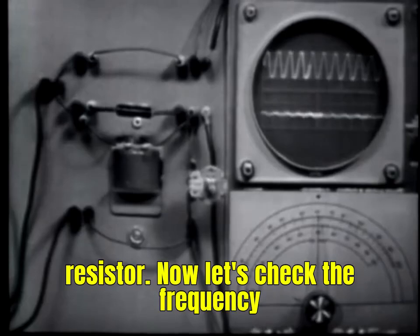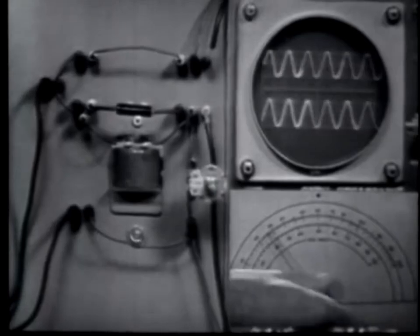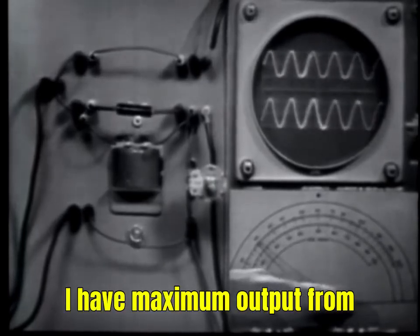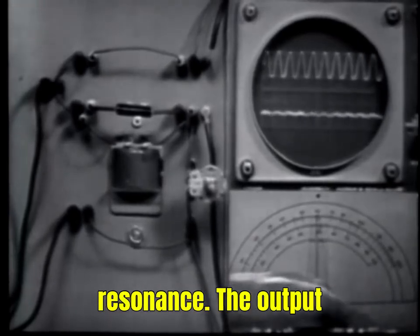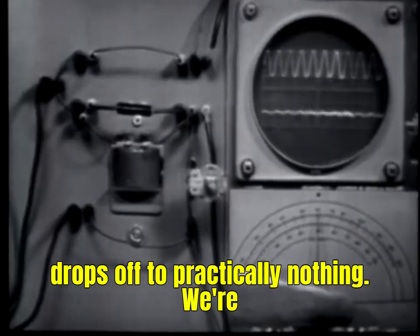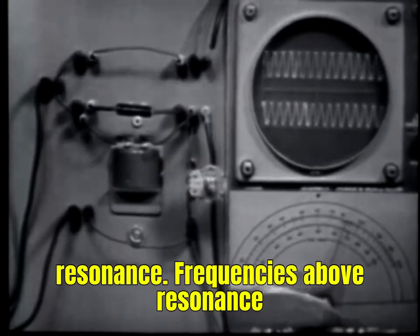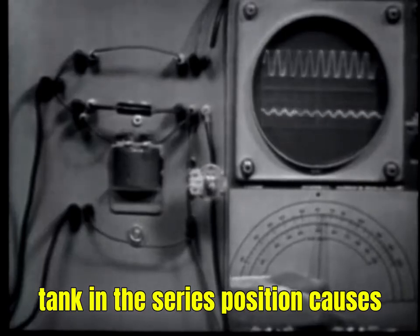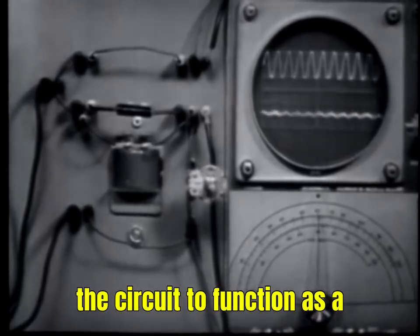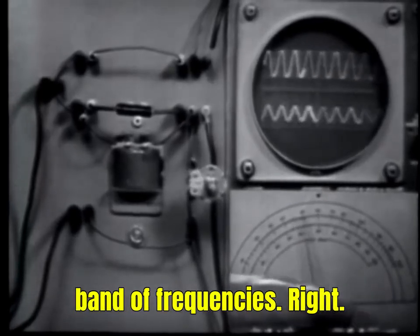Now let's check the frequency response of this circuit. At low frequencies, I have maximum output from the filter. But right around resonance, the output drops off to practically nothing. We're rejecting these frequencies right around resonance. Frequencies above resonance are being passed. So the parallel tank in the series position causes the circuit to function as a band reject filter. It's rejecting a band of frequencies right around resonance, but passing all others.